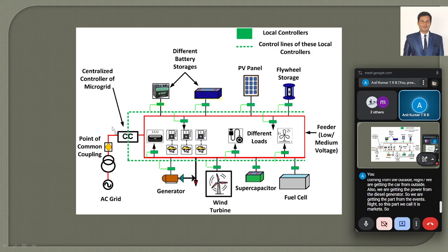So in this smart grid, even if the AC grid fails, whenever this gets disconnected, right? You can get the supply from here also. So there is a chance of disconnecting and connecting. So this is one component. PCC, we call it a PCC. The point of common coupling is one component, right? Where the various points can be connected. Your grid is also connected, right? And we also have the physical disconnections, right? From 11 kV to 415 V we can also do connection and disconnection. So all right, that is one of the main things.